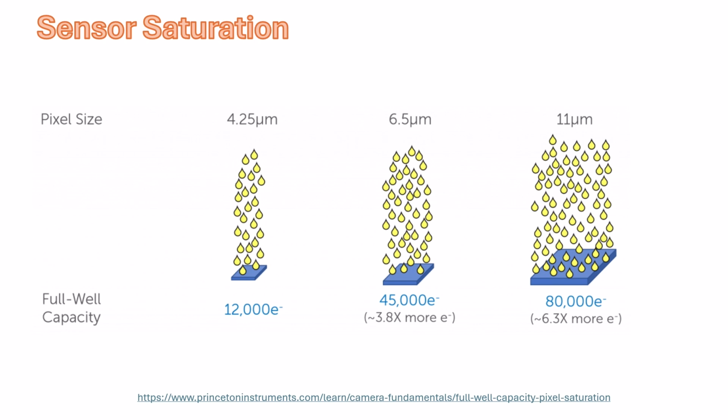And that's plenty to describe what you get out of a focal plane. Unfortunately, it's not nearly enough to describe the dynamic range that we'd see in a scene, ranging, as we said, from looking at something that's solar illuminated to something that might be in the shadows. We might have 8 orders of magnitude of dynamic range in the illumination of a scene, which would require us to have 28 or 30 bits to fully describe that.